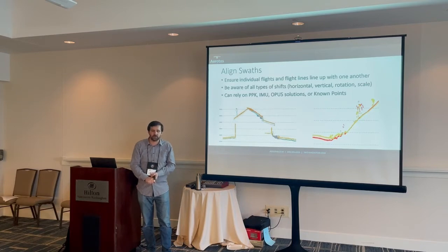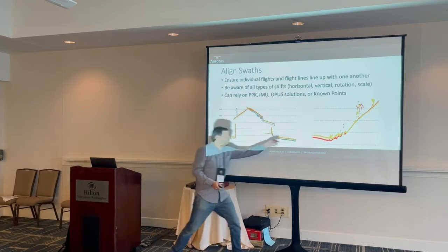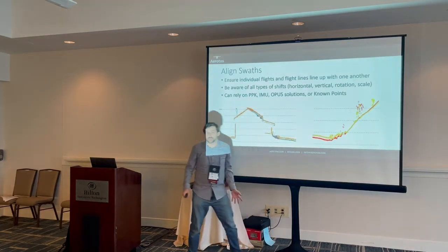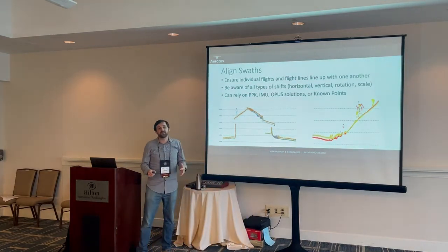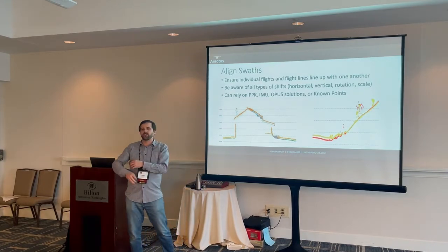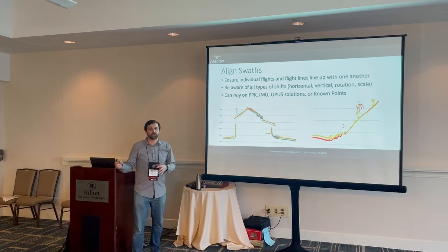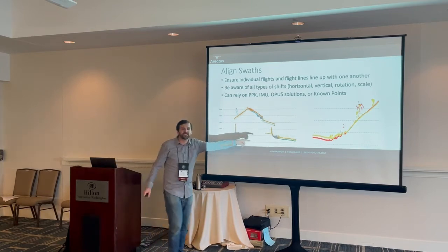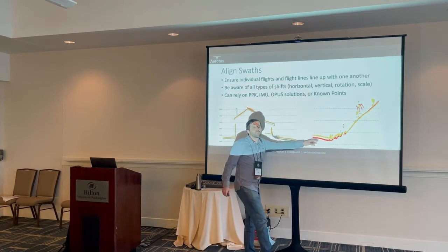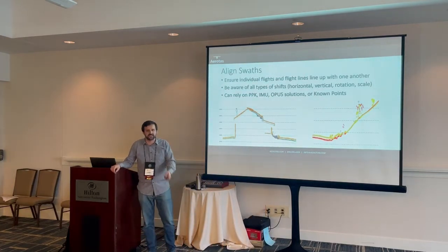You can use network-based corrections, which, if working properly, shouldn't show anything like this in your GPS data, but sometimes you do. If you have longer baseline distances and your tropospheric correction errors are consistent in one direction from one day to the next, you can still see this type of thing with network-based corrections.